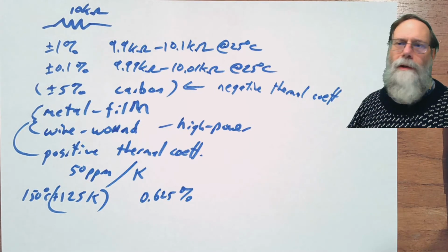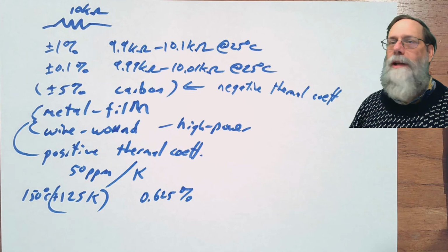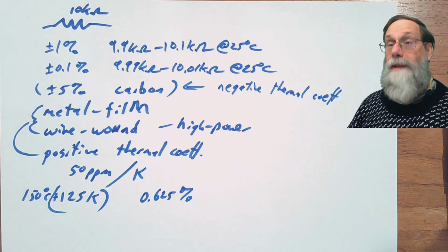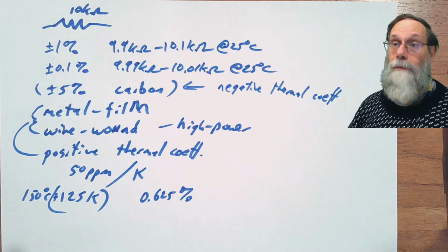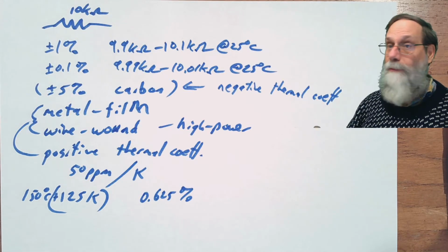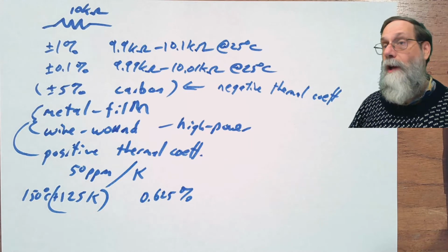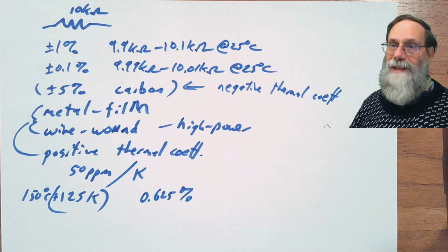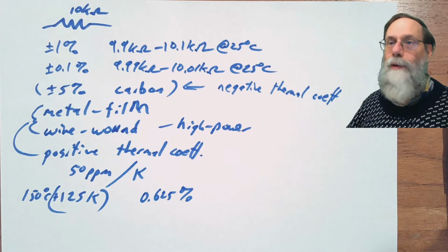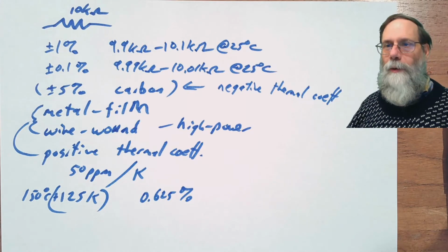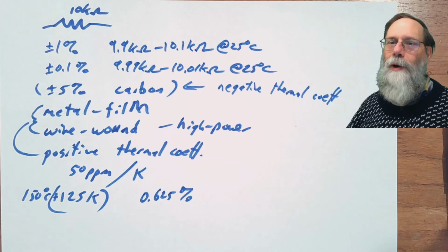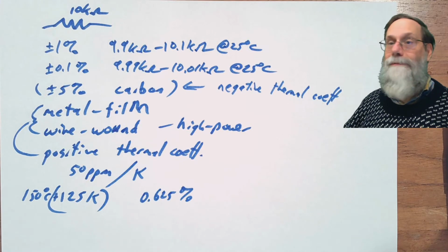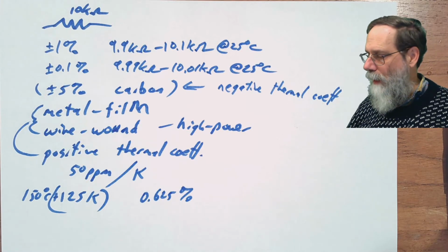So some of the very early electronic synthesizers, the stuff from the early 60s, was designed around carbon resistors, and if you take exactly the same circuit and replace the carbon resistors with metal film resistors, you may find it doesn't work exactly the same way, and that as temperature changes, it may go out of tuning, because they went to a lot of work to make the thermal coefficients of the resistors compensate for changes, and now it's not compensating in the same way.